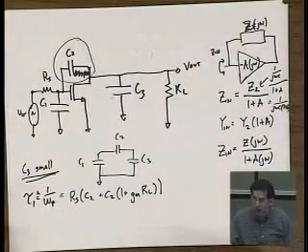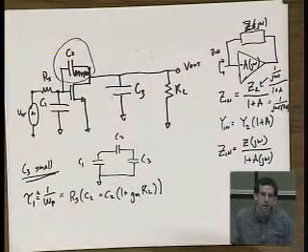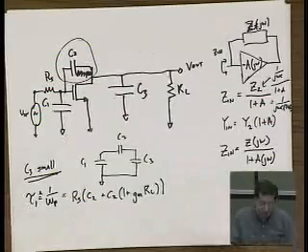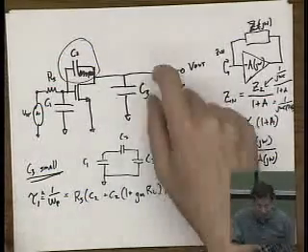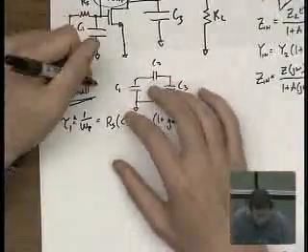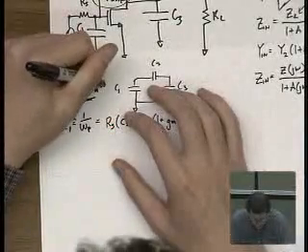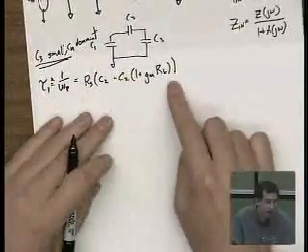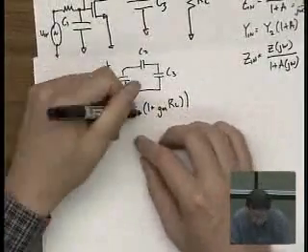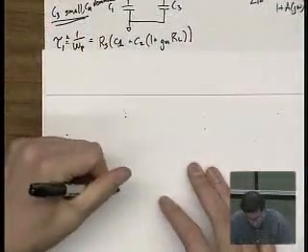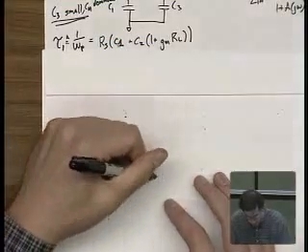Now, in office hours, just about everyone who came in to talk about the homework got tripped up by this: in this kind of circuit, what's the non-dominant pole? It's at the output, right? So at the output, the assumption here is that C Miller is the dominant one, right? Basically this C2 times 1 plus gm RL, this is C1, this is C2, is going to be the dominant factor. So now, for the output pole, I'm going to just redraw the circuit.